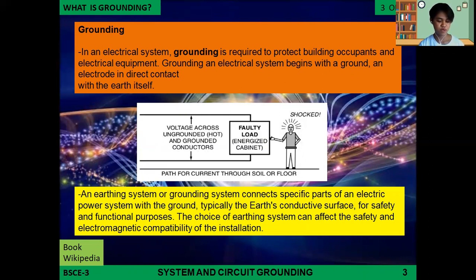Grounding of an electrical branch or circuit enables current to take an alternate path back to the overcurrent protection device if an electrical device or appliance short circuits. It requires an additional supplemental wire called the grounding conductor.